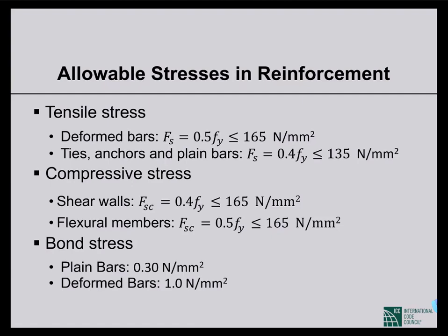So for masonry construction, reinforced masonry, we are quite conservative because we cannot depend on the bonding between the reinforcement and grout as we can depend on the bonding between reinforcement and concrete. The bonding will not be that reliable. That's why we're quite conservative, even for allowable stresses in reinforcement.